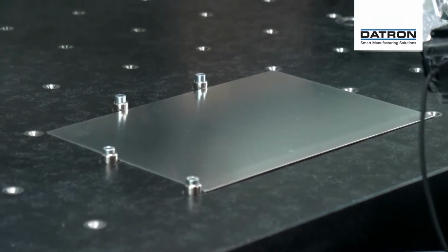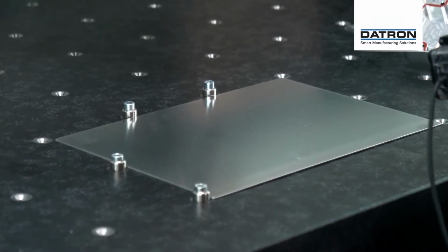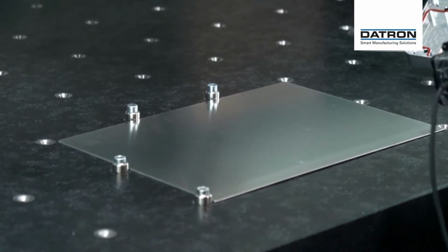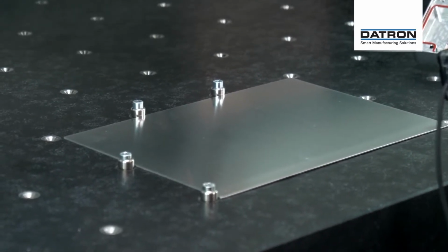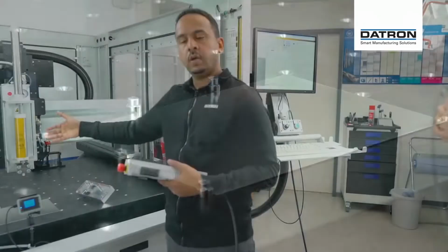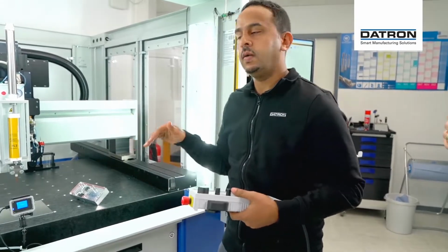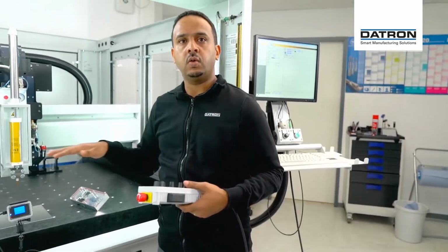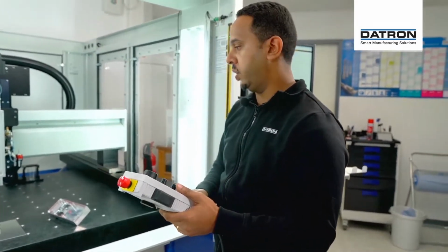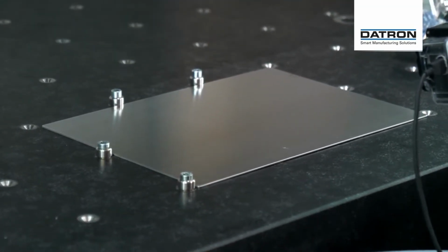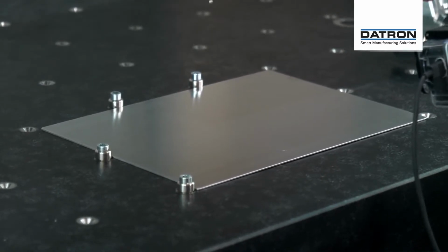Okay, so now the next aluminum plate is placed on the machine table. On the right side of our dispensing head, we have our mechanical probe. We are measuring the surface with the probe and correcting the height tolerance. And then afterwards, we are dispensing, or placing the gasket on it. So we are moving to the first point and then start to measure the surface.